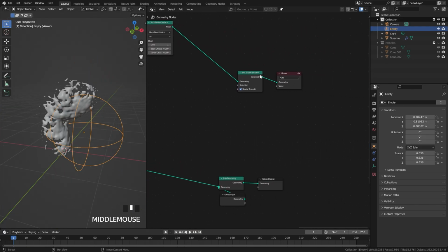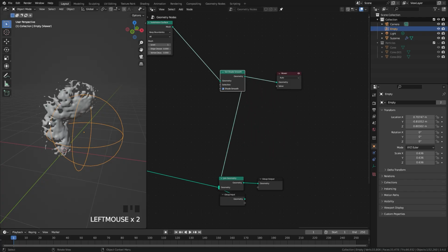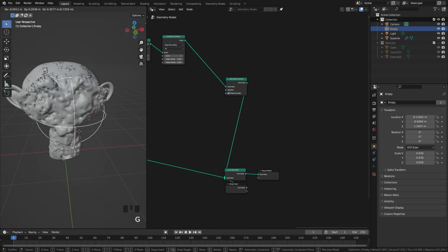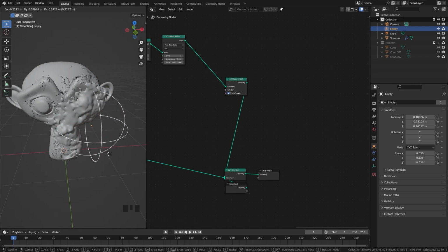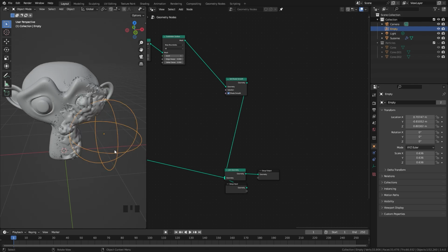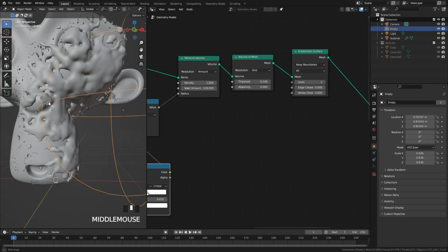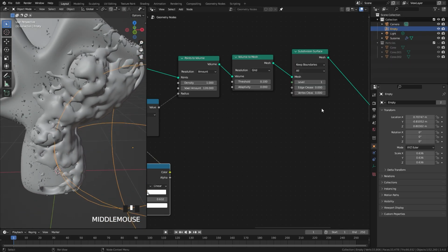Now what we can do is take that is shade smooth and plug it into the join geometry to see what the original mesh looks like and the particles as well. Here, let's get rid of that viewer node. Once we move this empty, you can see the particles are appearing, and so is the ice, and that is looking pretty cool. You might notice though that the ice is looking a bit too flat and plain, so let's also add some randomness to that as well.